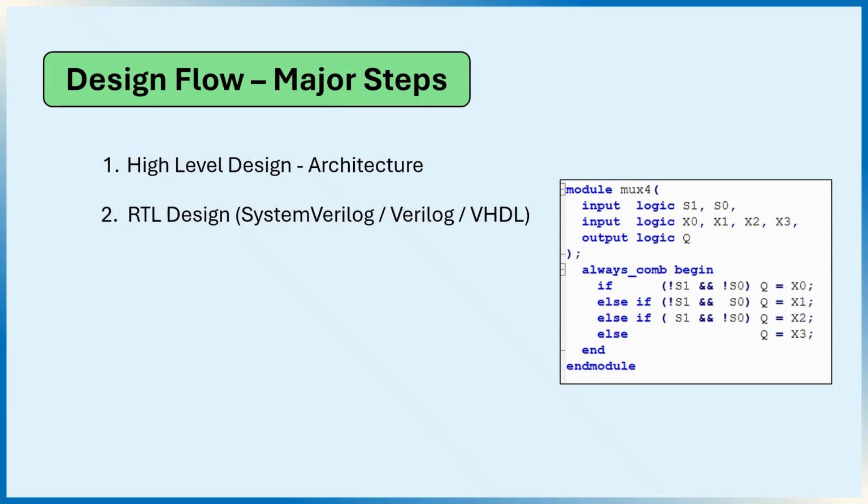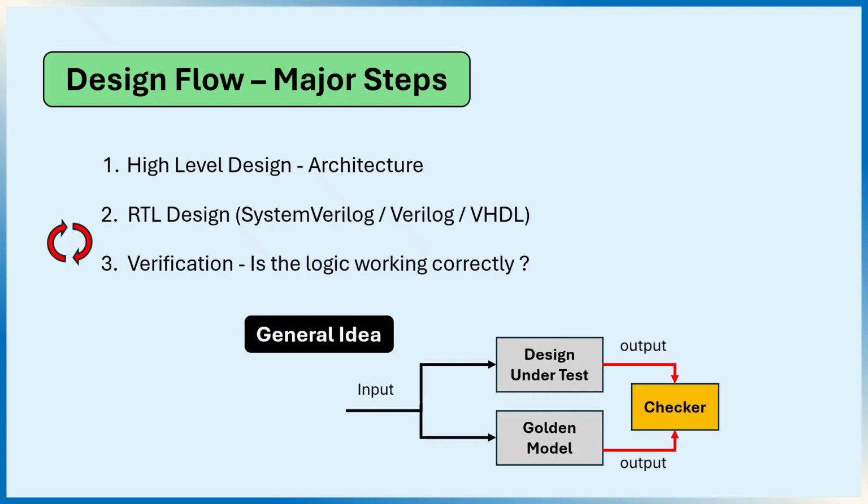After that is verification, where we check if the logic is working correctly. Verification is an iterative process that runs side by side with RTL design. You refine the RTL, run simulations, find bugs, fix them, and repeat until the design meets the specification.